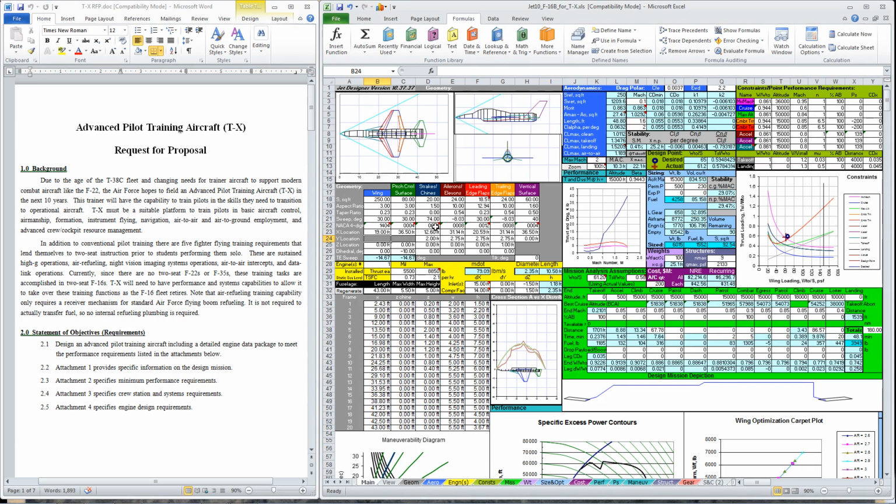Let's reduce the sweep of the strake a little bit so that the rear end of the strake lines up better with the leading edge of the wing. Let's try 73. All right, well, a little was good. Let's try a little bit less sweep. Let's try 25. And once again, 25 dropped the mission fuel burn. It lets us go to 14,900 pounds.